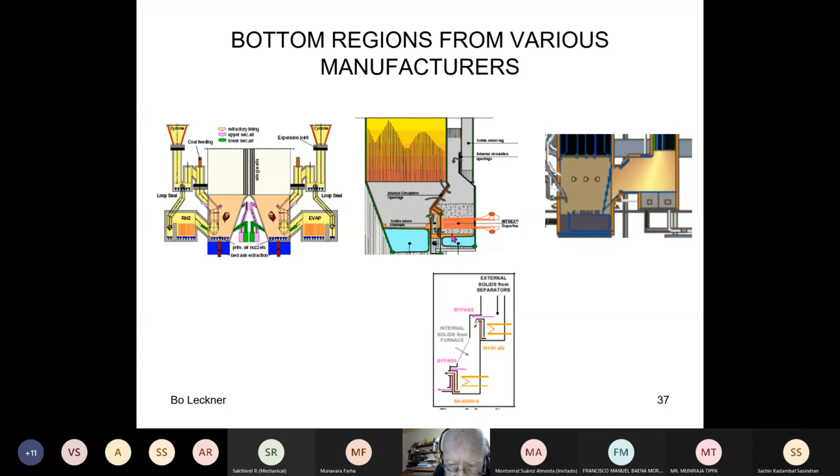Here in the bottom there are nozzles, and now you can see the tube that is bent to form the bottom. Then the tube goes down around this bottom space and to this header. So there are tubes going straight to the header, but some tubes are bent away to form the bottom, and they form also the wind box.